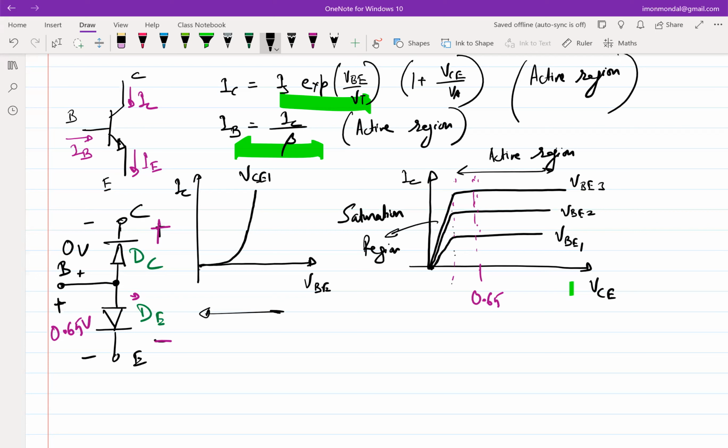However, to truly get a diode operational with a certain amount of current, 0.1, 0.2 are typically not sufficient for the typical currents we use. Generally, those ranges of currents you get if you reach at least 0.3, 0.4 volts of forward bias. So essentially, this knee is about 0.3, 0.4 volts away from 0.65, so this is approximately 0.2 volts.